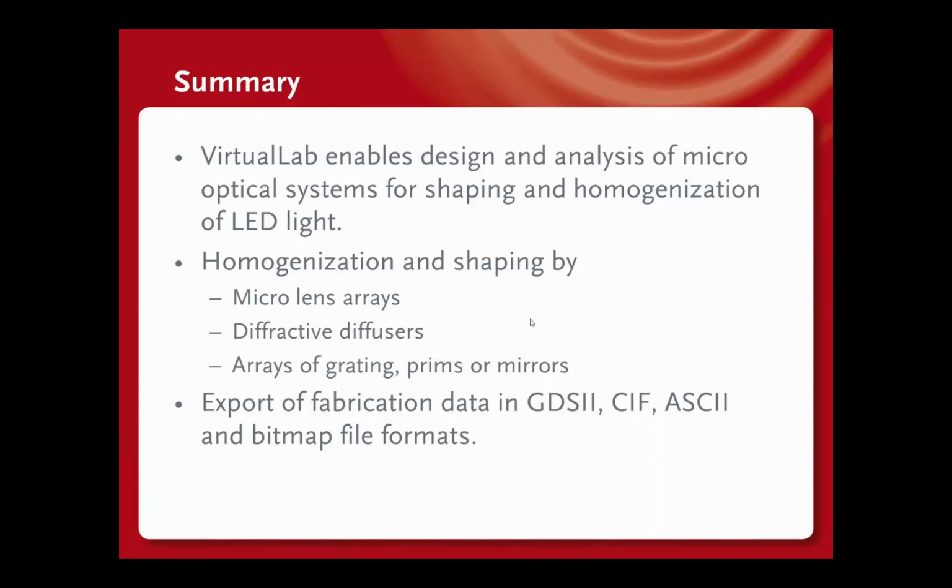The full simulation of the optical setups with these micro-optical elements is done by unified field tracing, and this includes diffraction, interference, and partial coherence effects. And I showed you that you can export the surface profiles in different data formats, and especially for etching of DOEs and microstructured surfaces, GDSII files, ZIP files, ASCII and bitmap files are of importance.